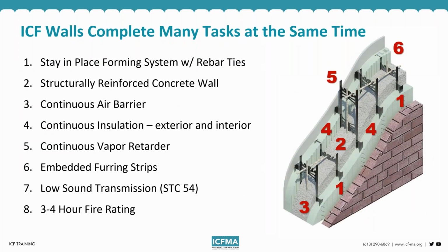An ICF wall completes many different tasks at the same time. So as we kind of talked about, this is, again, a stay-in-place forming system. And so it takes the place of traditional forms that you would remove after a pour. You have a structurally reinforced concrete wall. So the rebar fits in on the plastic ties, and most of the time those ties take the place of having to tie all of those individual rebars by hand. So you can snap those in place, and that saves some time and labor.